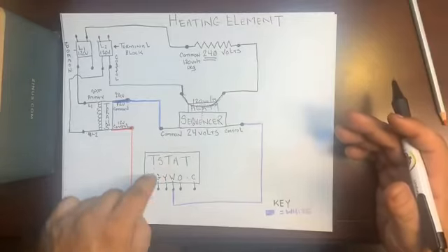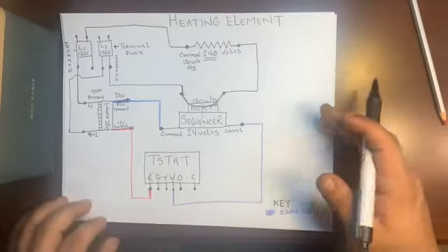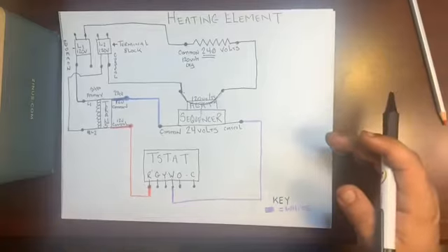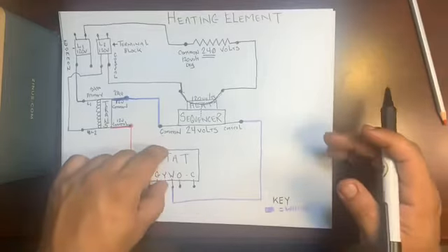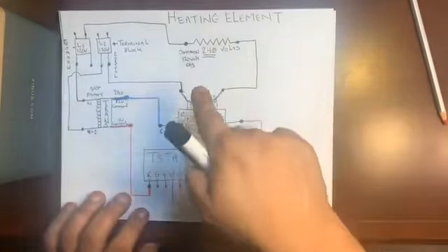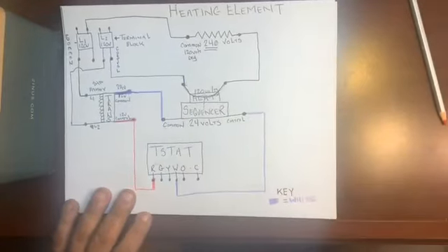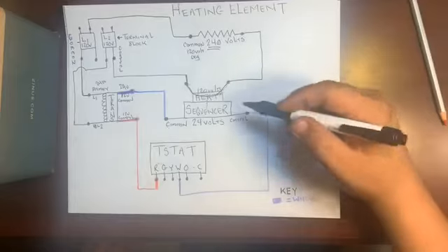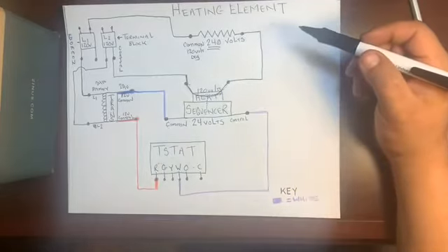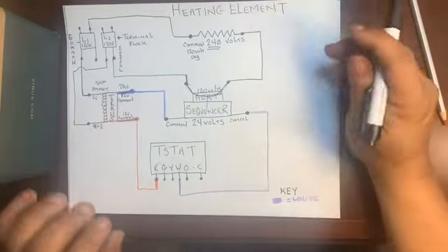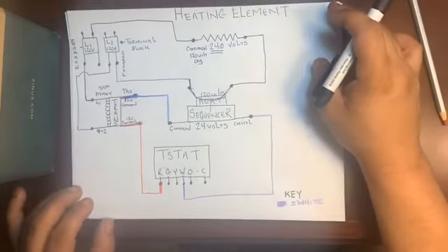If not, you'd have 120 volts and homeowners would be electrocuting themselves. Because it's the equivalent of taking the wall plate off your wall and sticking your finger in there, if a homeowner pulled the thermostat and started touching it. So this is the heat sequencer in action. Let's go ahead and go through our diagram and learn a few more things.